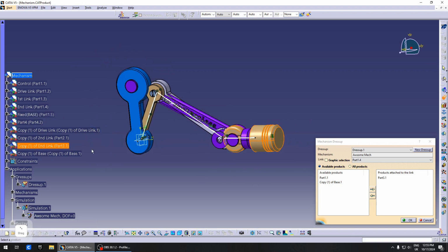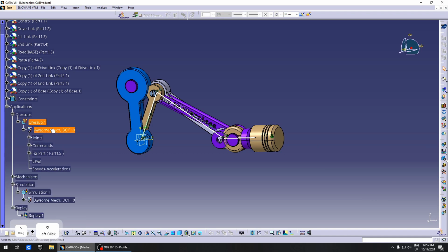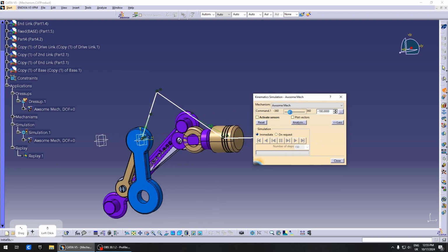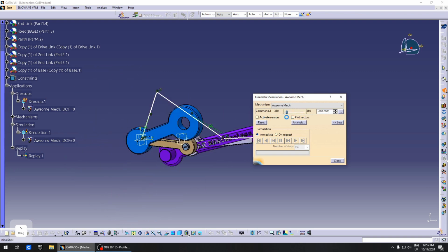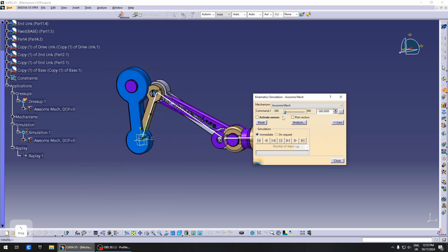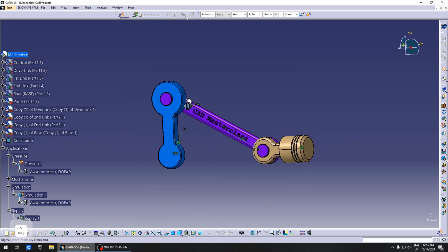You could do anything else. You want to add some parts to design it. It doesn't have to be the same or similar. It's basically just connecting two parts together. And now we have our Dressup for this mechanism. And if we simulate this, you can see that the parts from my original mechanism will follow the rotation. You can go ahead and hide the previous one and hide the screw as well.